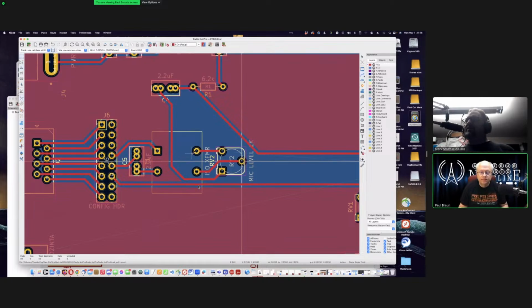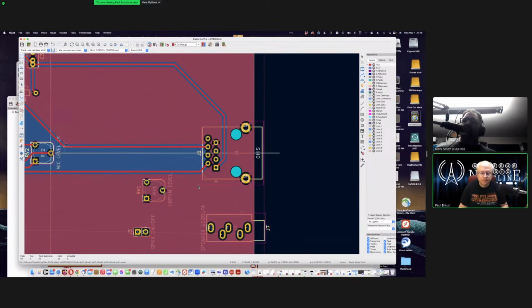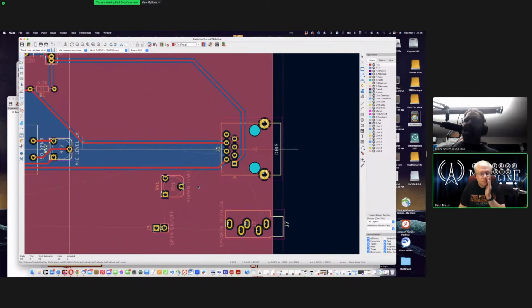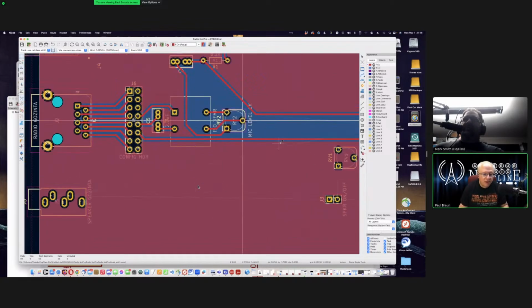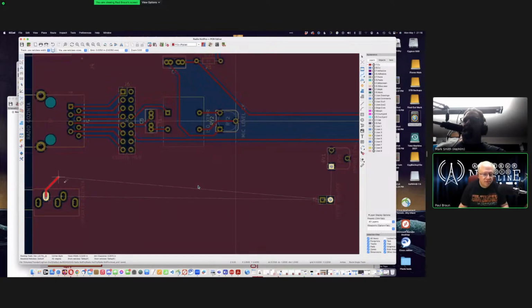Scroll over to the right. I want to see what happened to that PTT line when we dragged it down. Oh, yeah, that's fine. That pulled out there. All right, so now we have this big area in the middle where copper pour didn't go. So let's drop some vias there. We're not done yet. Okay. Yeah, let's go ahead and finish up first, because there will be more of those. I'm seeing ugly lines, so this is going to have to come down.